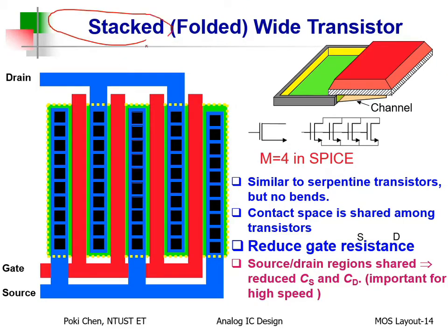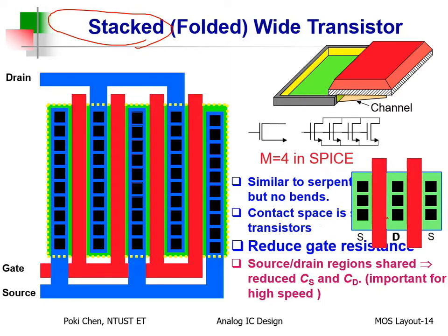Okay? With such kind of stacked layout, we have a lot of benefits to reduce the parasitic capacitance by overlapping. While I'm telling overlapping, allow me to show you this. One finger, the other finger overlapped in this region. Okay, before overlap, you can see I have sidewalls, right?